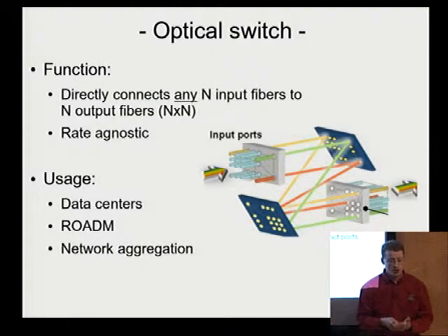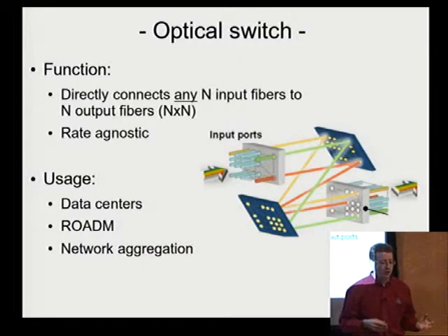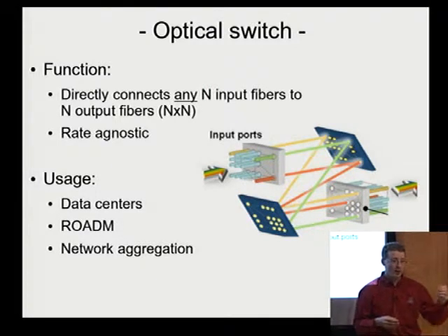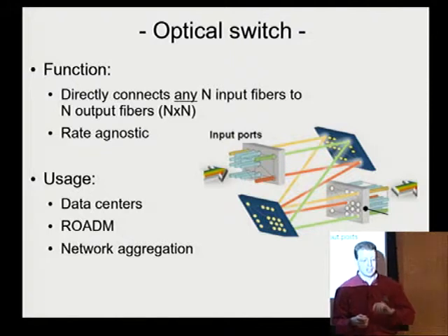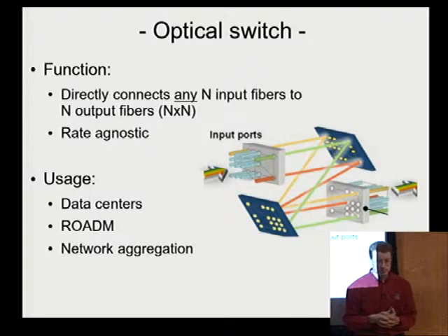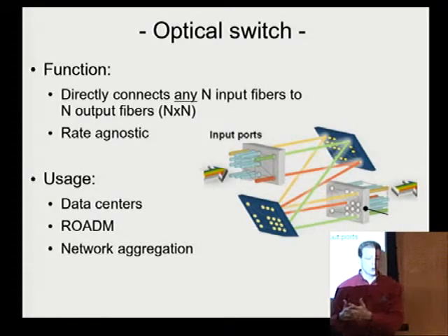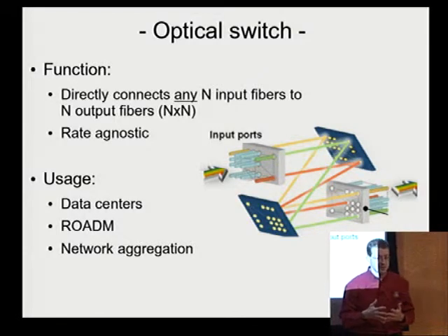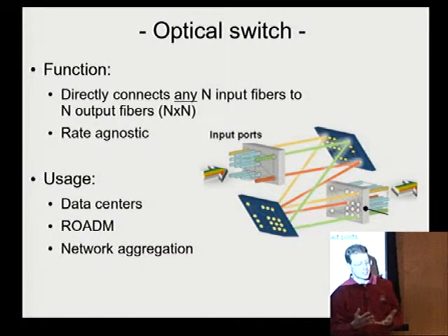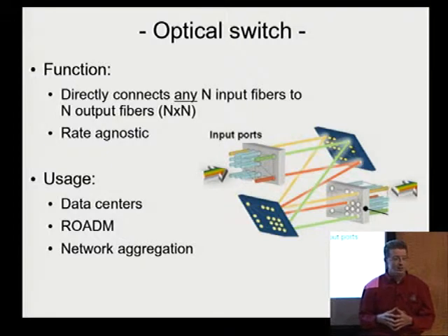This switch function can be done with a detector converting photons at one end and transmitting the signal into an electronic box, and then firing a laser at the input of the correct fiber at the other end. So these switches are called OEO, for optics, electronics, optics. But their response is limited by the electronic bandwidth. And we know fibers are far better than electronics. So these switches are a bottleneck in the data communication architecture.